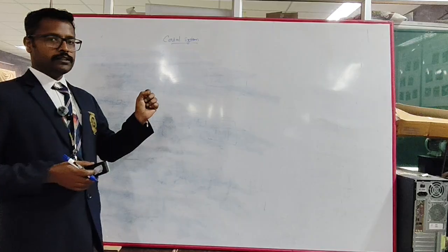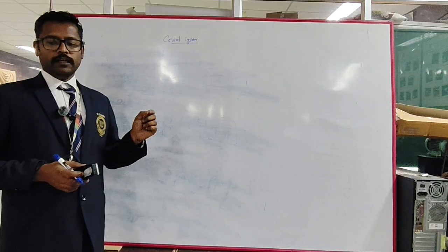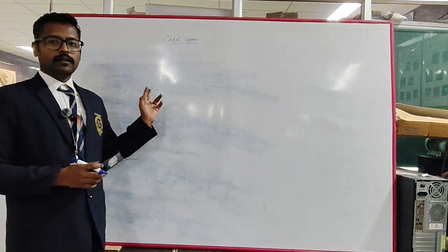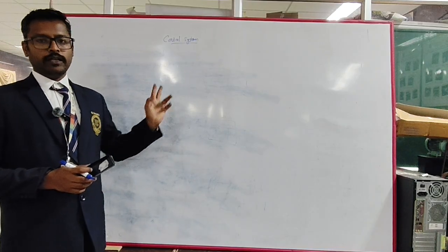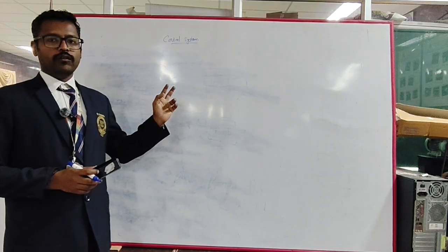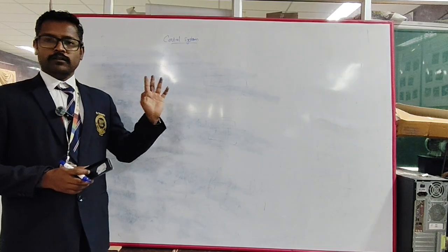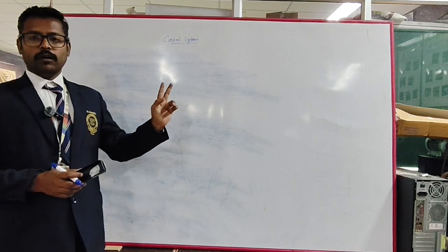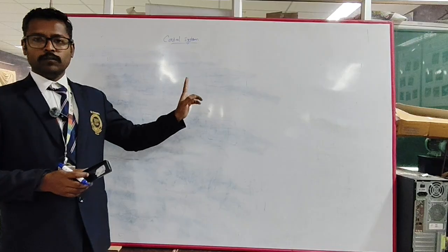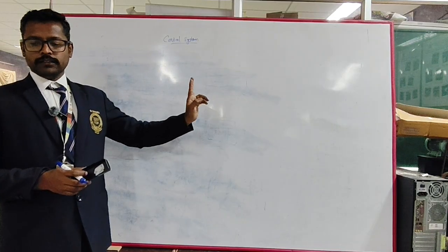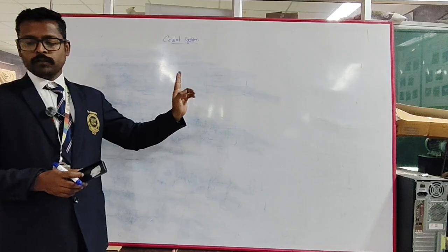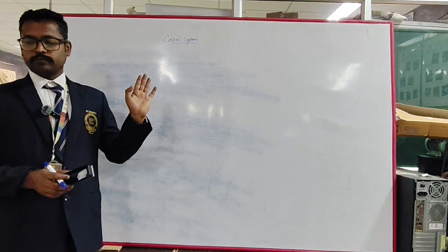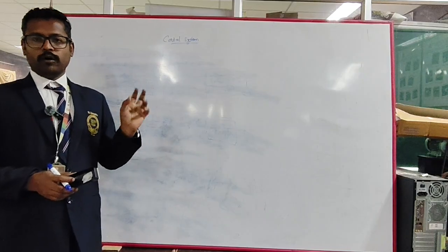In the rules for reducing the block diagram, we have seen that there are 10 to 11 points. The first one is combining blocks in series, where we multiply. When the blocks are in parallel, we just add the gains. Then moving the branch point ahead of the block or before the block: if the branch point is moved ahead of the block, we multiply with the inverse of the gain, and if moving before the block, we multiply with the block gain.